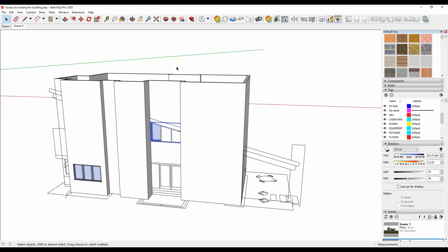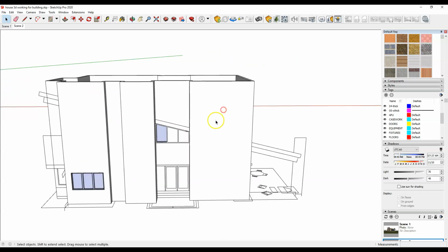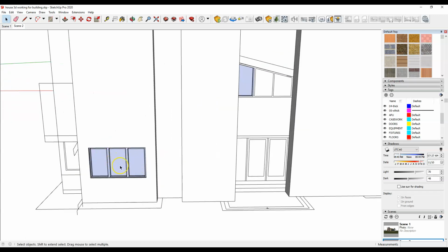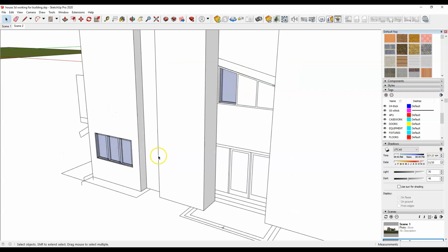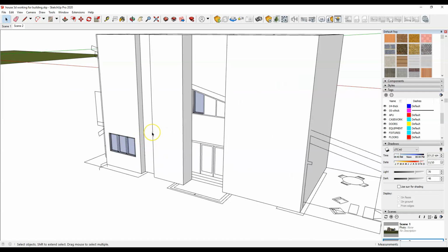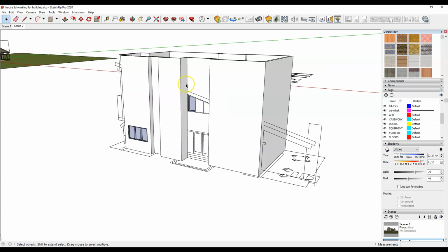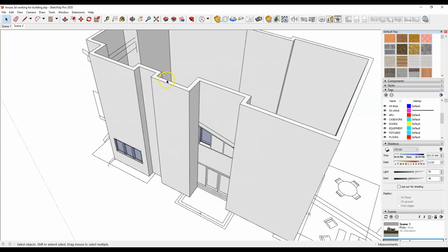I don't remember at this point, but the point being basically walls all the way up, punch the windows and the doors in later. All right, now one of the things I want to step back and talk about is the fact that we got gray and white, and this is an important concept in SketchUp too. SketchUp allows you to work where the gray is the inside surface and the white is the outside surface. So I could have built this house without double thick line walls, but I didn't want to because of windows and other such things.